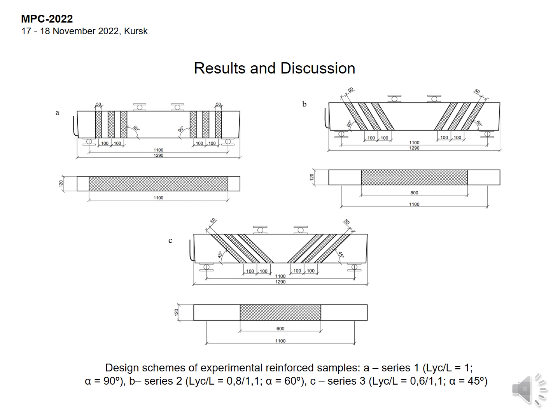Firstly is testing of auxiliary concrete samples of the design class for compressive strength B15 in the form of cubes and prisms for compression, bending, determination of the initial modulus of elasticity.